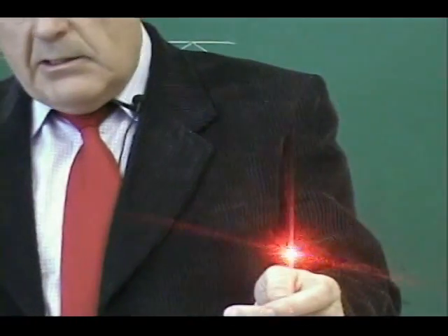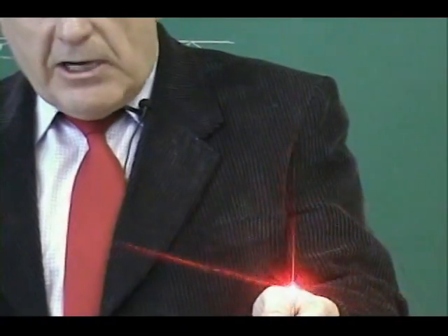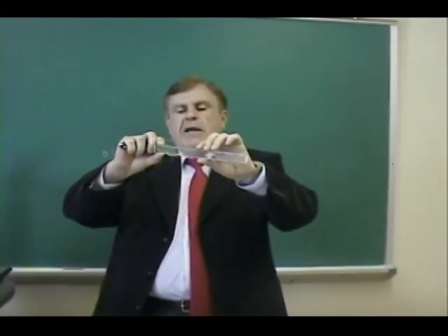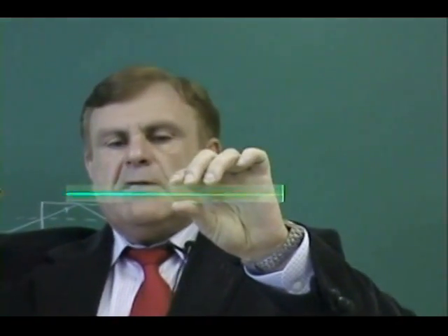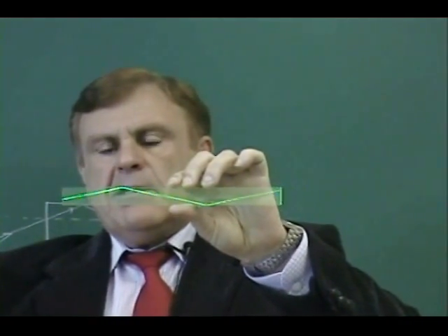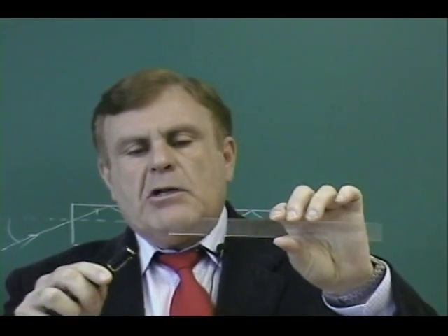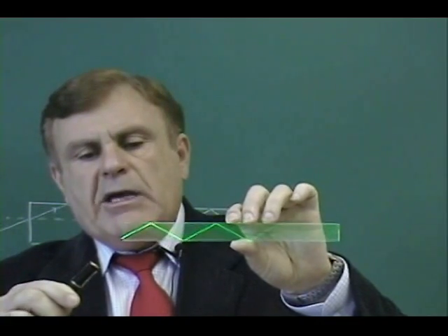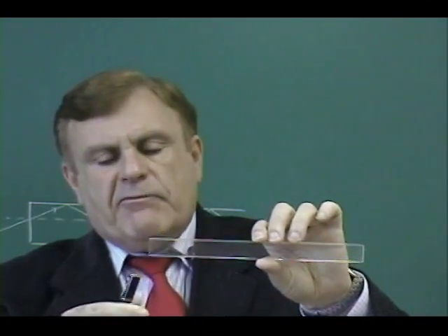And the first thing, we will measure the numerical aperture of this fiber, and I will first tell you what it is about. As you know, light is reflected along this fiber because of total internal reflection. Here you see a light go straight, but if I incline this laser pointer, you see how the light bounces up. But it only will occur if the angle is larger than the critical angle. So if my angle is smaller, the beam will not be bounced, it will escape from the fiber.